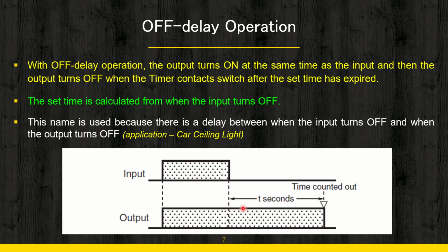Still your output is under actuated condition. After a preset amount of time, the output is turned off. Here what is happening? The turning off of the device is delayed. The turning off of the device is happening after a preset amount of time or after a delay. Therefore, this is known as off delay operation.